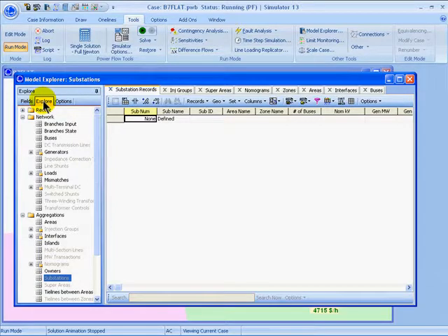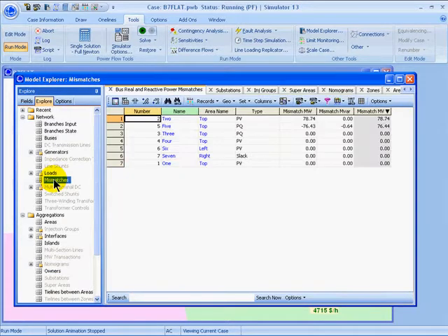In the Explore tab, inside the Network group, click on the mismatches. These are sorted in descending order, and we can see that at bus 2 and bus 5 we have a mismatch equal to the flow that was on the line before we opened it. The mismatch display also shows what type of bus each bus in the system is: PV bus, PQ bus, or island slack.